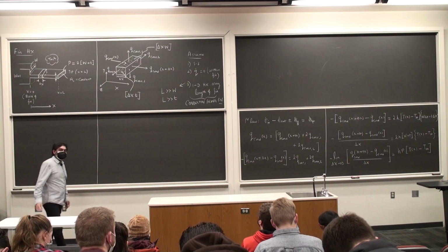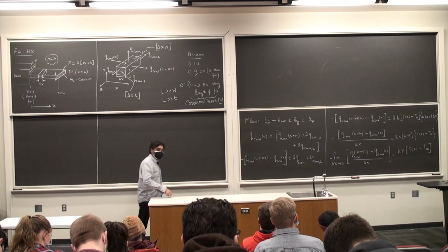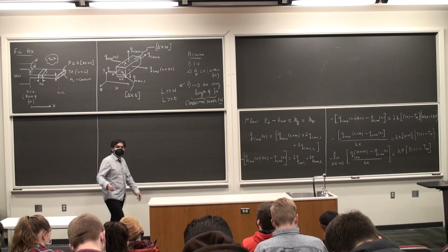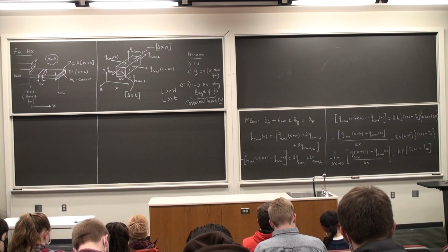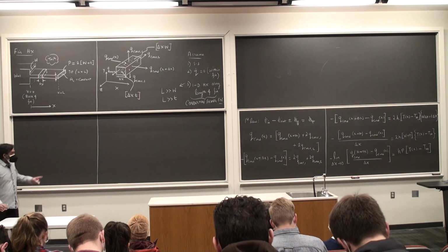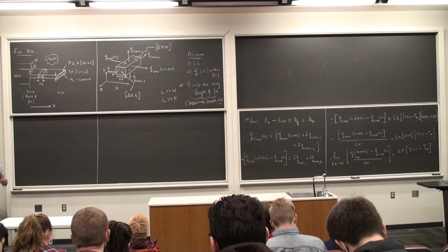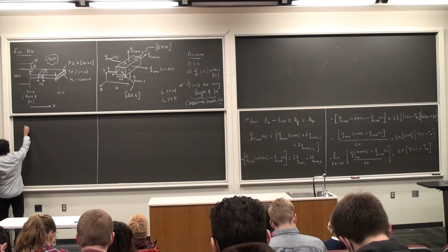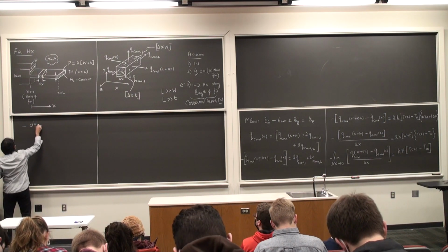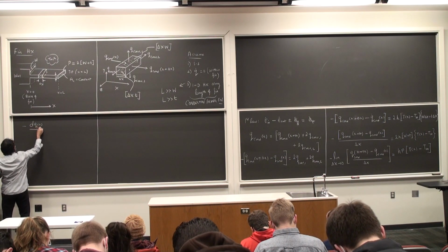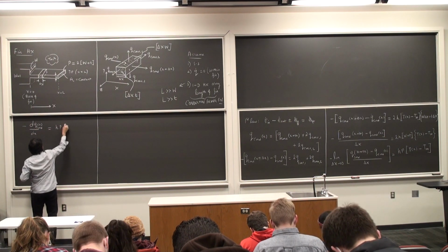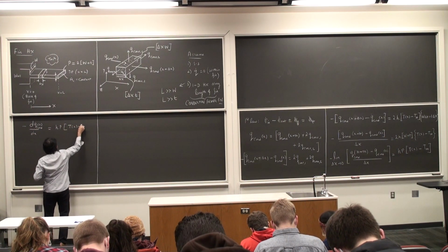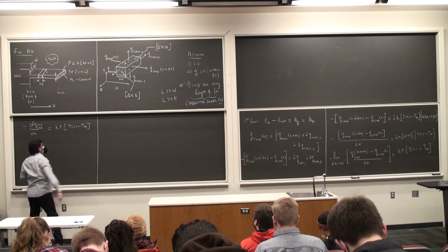We use the same idea for obtaining the heat diffusion equation as well, for plane walls as well as for cylindrical bodies. So this is exactly a similar type of analysis. And in the limit of delta x tending to 0, that becomes a differential quantity. So I have minus dq conduction by dx is h times P times T of x minus T infinity.